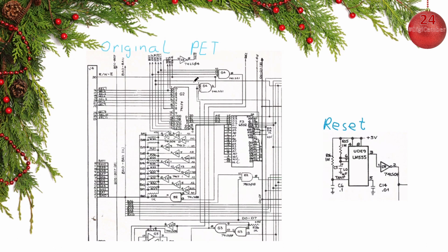But here you can see an old acquaintance of ours to do the selecting of the chips, the chip selects. This is the 74154 device that we used earlier. So this is the 4 to 16 decoder that we used in our experiment on the breadboard earlier. Here it is used as a chip select device, and you can see that they take the A12 to A15 into this decoder to make the ROM and IO space probably decode.